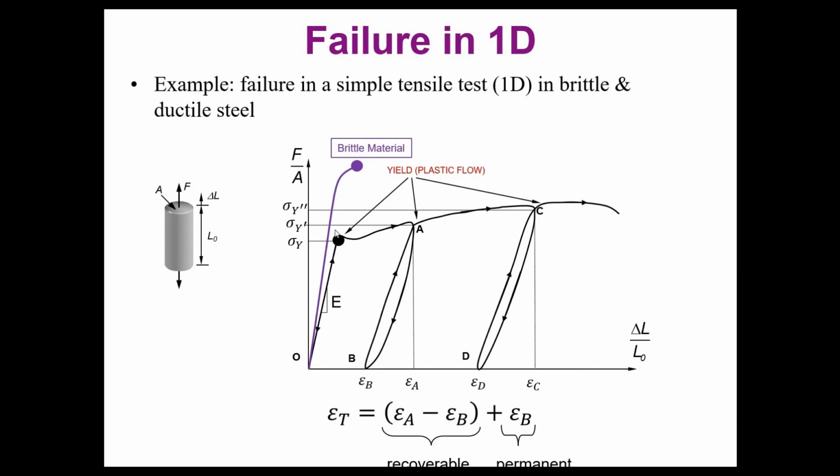And you notice that the first stage for the brittle material was linear and elastic, and probably what you are going to notice in the lab is that this curve here will correspond to a non-linear elastic behavior, because if you unload this steel before breaking the bar, you are going to probably recover almost all the deformation you had after the process of loading. In a ductile material, as you see on the screen, this is not what happens.